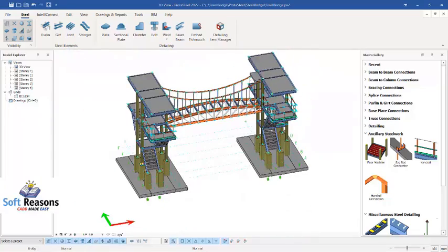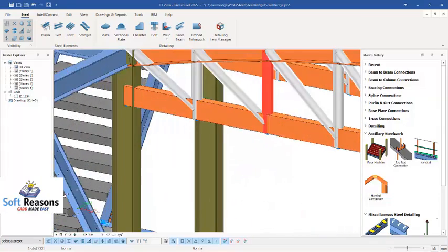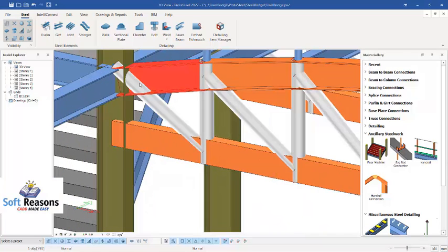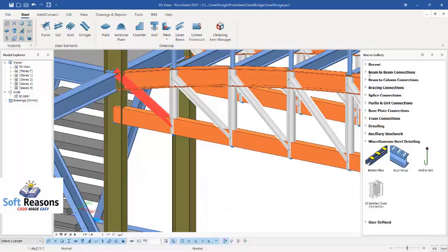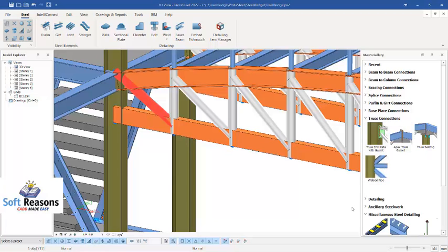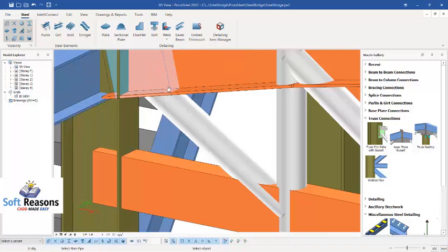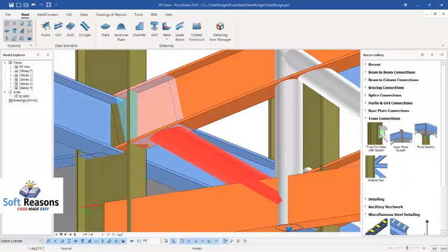After which the next thing is to look at this part of this bridge successfully. For this part of this bridge, you see these two members' connections. What you have to do is navigate to where you have brace connections, truss connection. Select this. We want to use welded pipe. So after we select this beam and then select this pipe, right click, and you can see it welded successfully. You can now see it's been welded successfully.